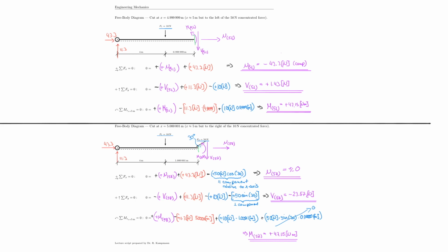I could have created the system here where I cut the same part, but I now introduce actually only the force here, which is, I believe, 23.57, and then I cut right here where I will bring in now my internal forces, my shear force, my normal force, and my moment. And if I use those, then I would find the exact same answers.